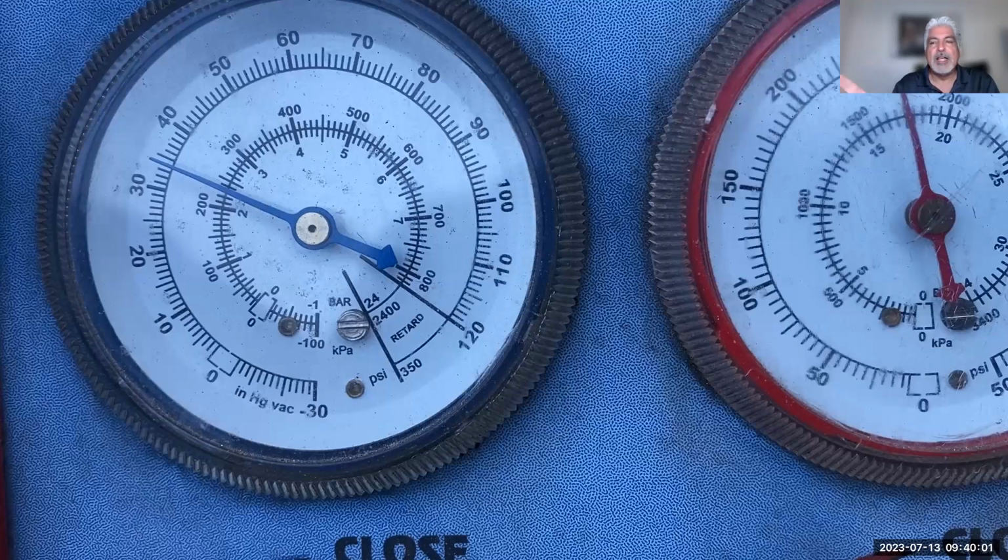Now I should see the high pressure drop, because I shot across the condenser. That refrigerant is now subcooled big time. It's in a liquid state, but it's going to run mega cold for about 20, 30 seconds. I should see at first the low pressure gauge drop, then it should rise dramatically.